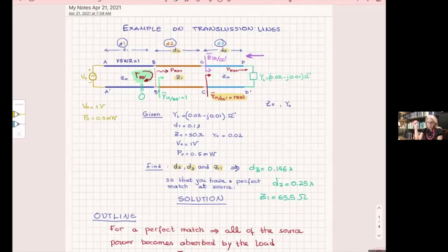Stick with the fundamentals in the Smith chart. That's very important. So if you want to go from impedance to admittance, go through the diagonal. Don't try to be on one Smith chart with multiple lines. The probability of reading the wrong number is so high that I cannot tell you. And you need to work with them every day of your life to be able to avoid that.